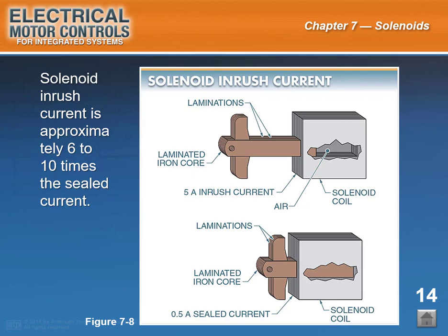The large amount of iron in the magnetic circuit increases the magnetic opposition of the coil and decreases the current through the coil. This magnetic opposition is referred to as inductive reactance or total impedance. The heat produced by the coil further reduces current flow because the resistance of copper wire increases when hot, which limits some current flow. End of slide 14.